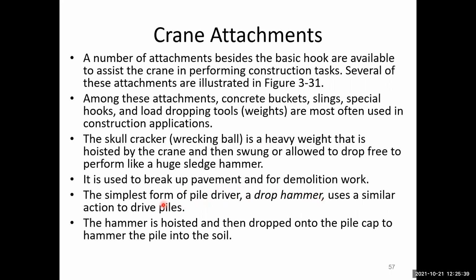The simplest form of pile driver, a drop hammer, uses a similar action to drive the piles. The hammer is hoisted and then dropped onto the pile cap to hammer the pile into the soil. So various types of heavy weight operations can be performed with the help of those crane attachments.